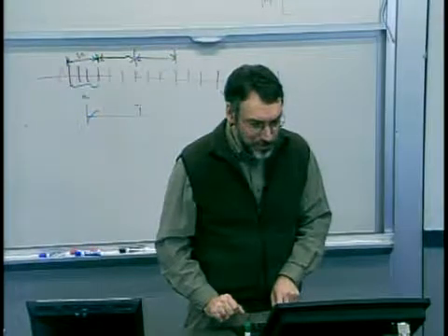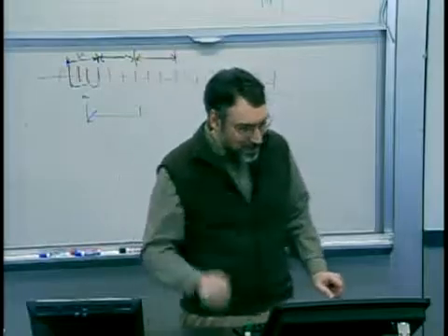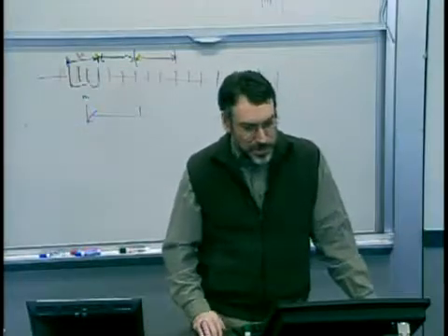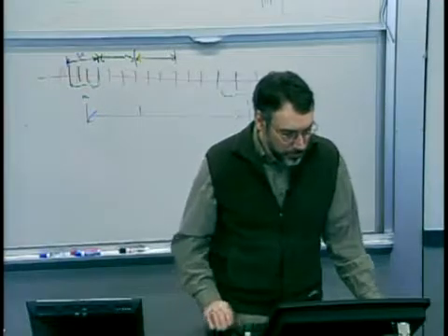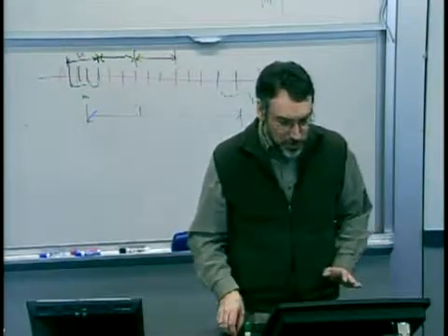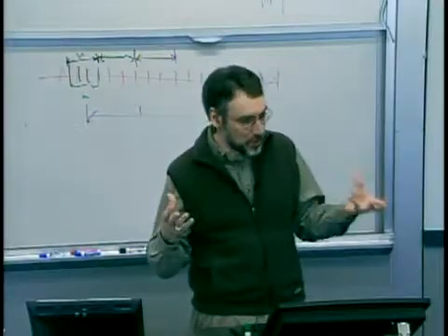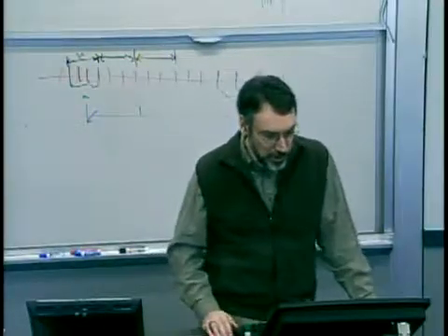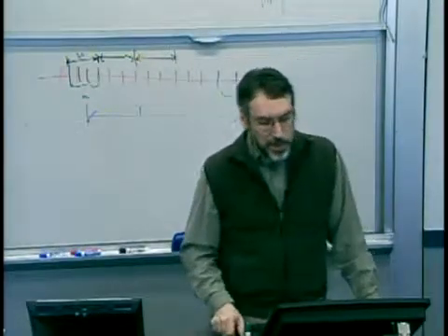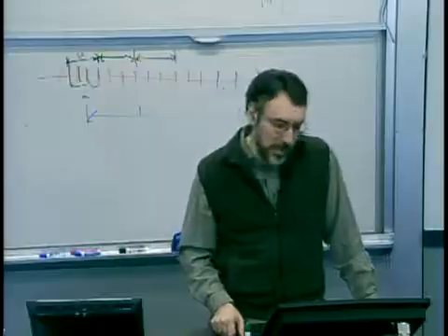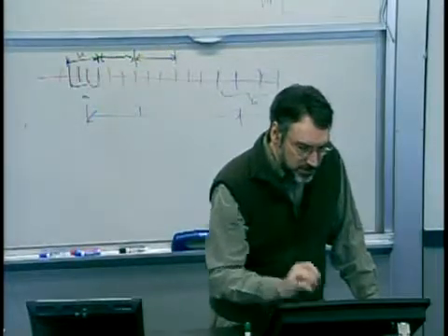I think this is trying to reveal a data point one at a time, which we don't really want to do. So here's an example. Based on what you've seen about an X-bar chart, and assuming here we've really set plus minus 3 sigma control limits on this chart, if you were moving along and just triggering on extremal points, what do you think? Was this an alarm?